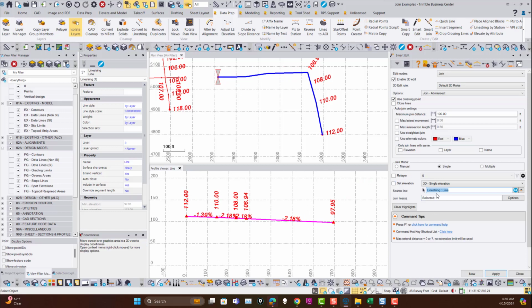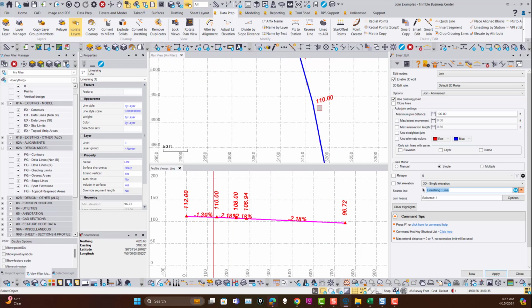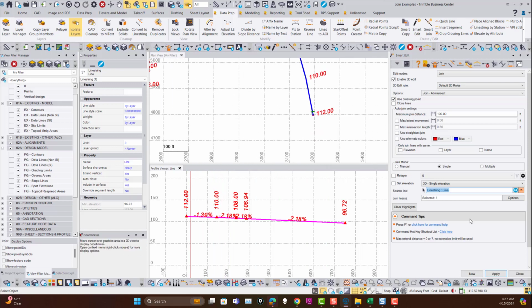So other things that you can do with that Shift M menu is you can pop it up and you can turn on the rock grip. So if you want to edit the line, you can come in here and you can now start making edits to the line, and then you can do Shift M again, and if you want to show the direction of the line, you can show the line direction. So that shows you the line directions on the line itself.